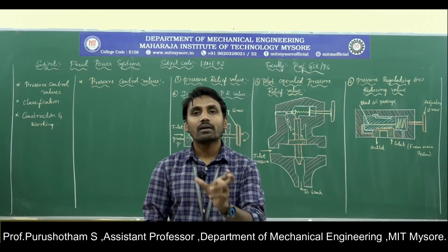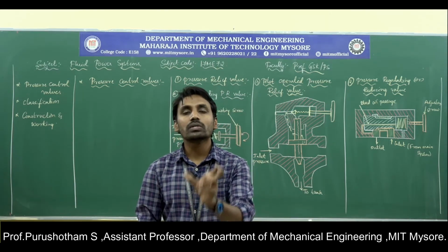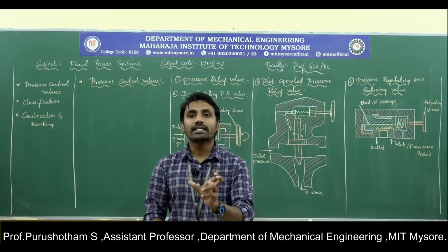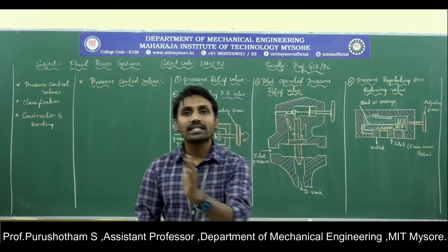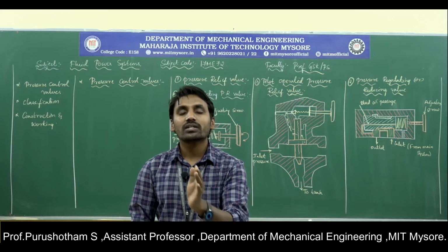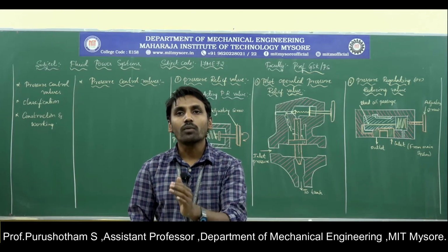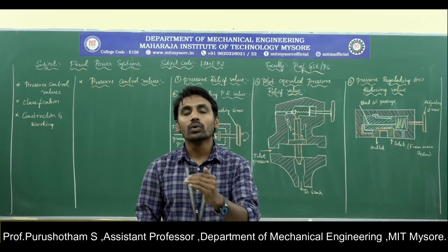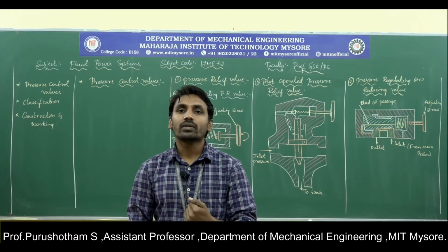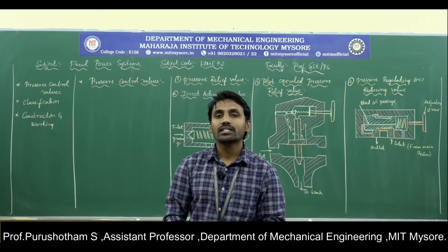In that case, the pressure control valve operates to limit the pressure so that it stays equal to 20 psi. That is the first one.